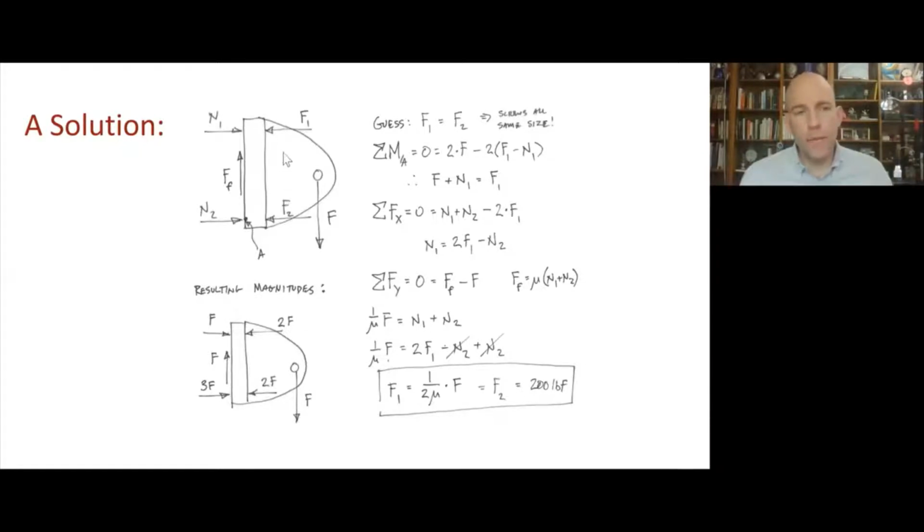Now it's true that maybe if we load this thing up, there could be some friction under the head of the cap of the screw, but the screw inside the hole will be a little bit long, so that deformation will have lots of room to occur, and it probably won't generate a very big shear force due to friction at the cap head.